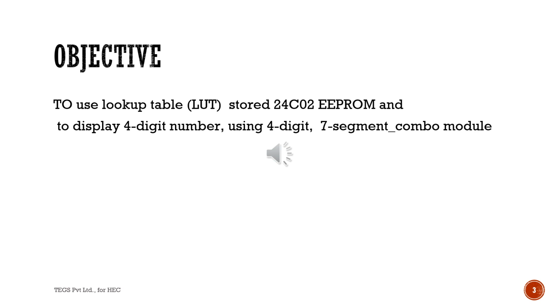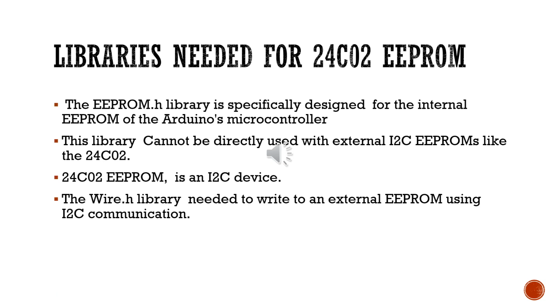The objective of the present work: to use a lookup table, LUT, stored in 24C02 EEPROM and to display a 4-digit number using a 4-digit 7-segment combo module. Libraries needed for 24C02 EEPROM.